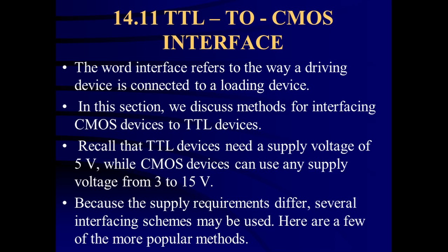What does it mean? If one of these logic family gates, maybe the TTL, is connected as a TTL driver, and the output of the TTL driver is connected to the CMOS IC input. Both logic families have different supply voltage ranges. TTL can work only on a 5 volt regulated power supply, plus or minus 0.25 volt allowable,